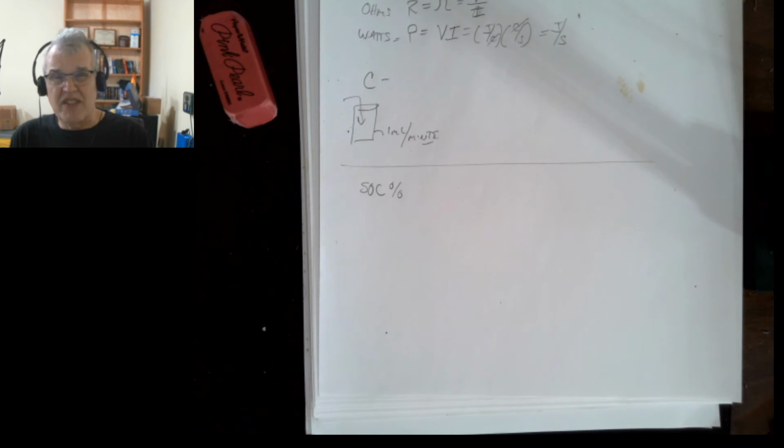So you want to make sure that the cells you put in there are good. They're probably under 4 years old. They have an initial potential, before you start messing with them, of greater than 2.5 volts, or 2 volts at least. And then you want to make sure that they have an internal resistance that is low, within specs that you want. And then you check the capacity to make sure that the capacity is up there at, say, at least 90%